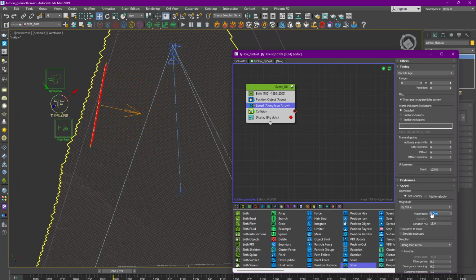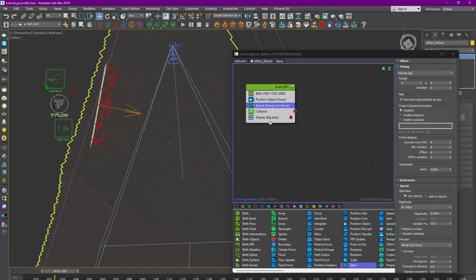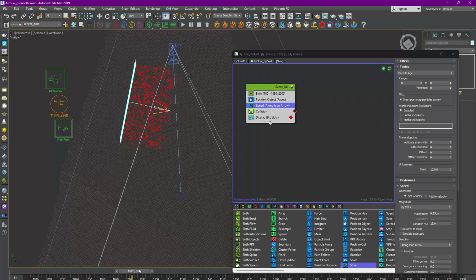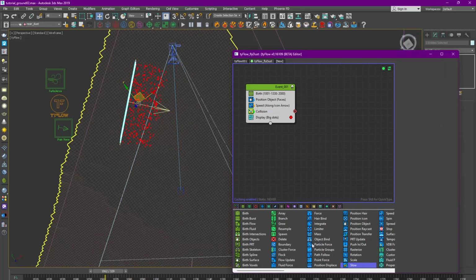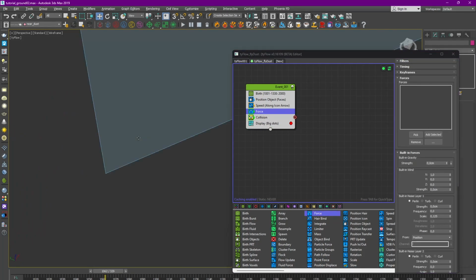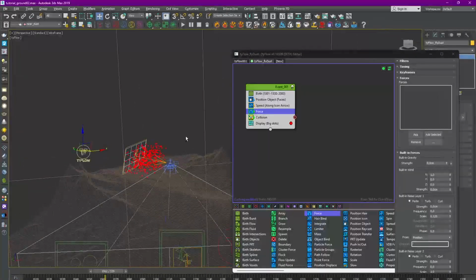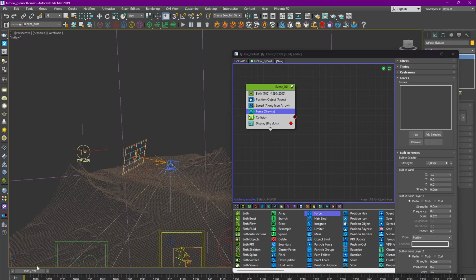As you see, the particle system also has a collision operator, and inside that collision I added our deflectors, which are from the previous chapter, to kill the particles outside the area of our emitter. Okay, next step. Also I will delete these test objects, we don't need them. Next step will be force. So the force will bring some gravity. Later we will tweak this value a little bit more precisely.